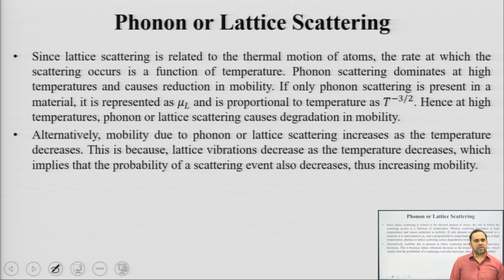If, say, in a semiconductor only phonon scattering is present, there is no other mechanism by which your charge carriers can get scattered, then your mobility is going to vary as T to the power minus 3/2, where T is temperature. Okay. So, at high temperature you are going to undergo a degradation in mobility. Or you can also say that if you reduce the temperature, mobility increases.